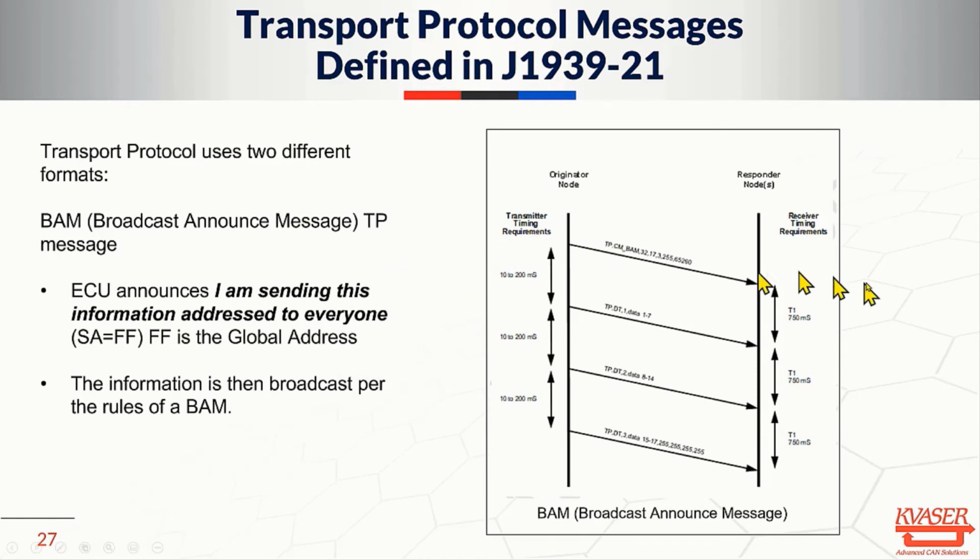There are two types of transport protocol. One is a BAM, which stands for Broadcast Announce Message. The originating node just simply sends the data in transport protocol format, and everybody on the bus receives it. That's the way a BAM works.